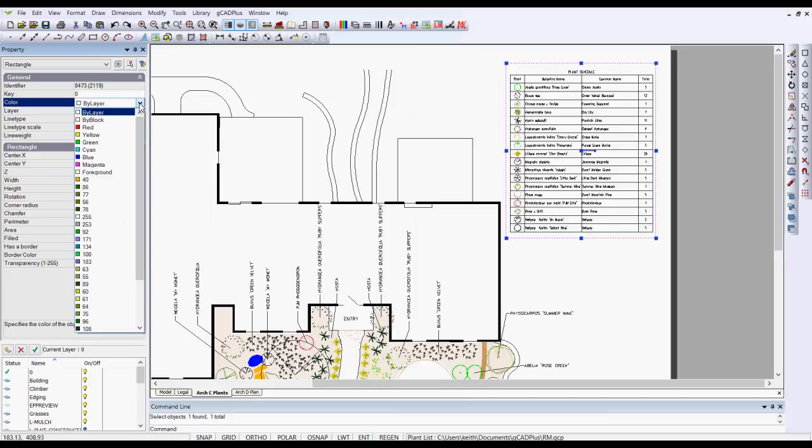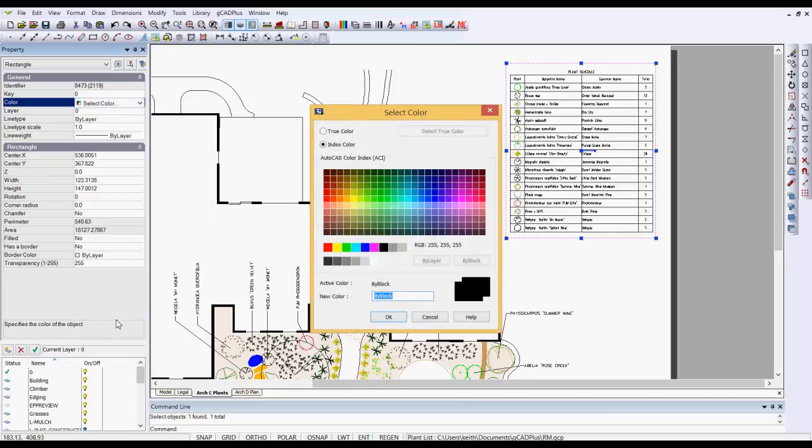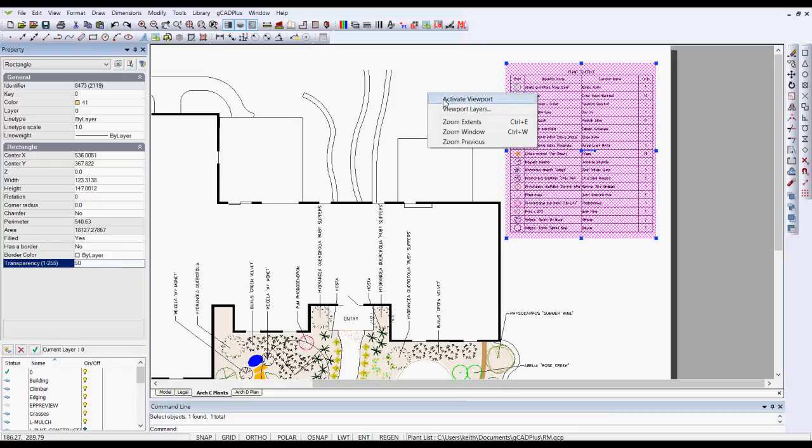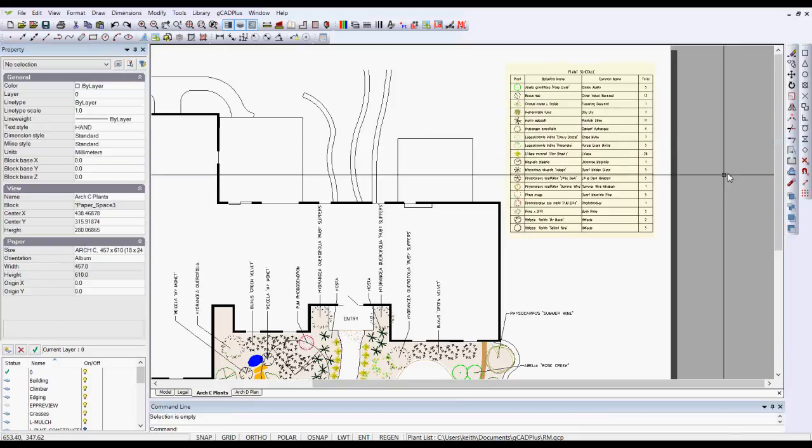We'll make the color of the rectangle some sort of buff color. I'll select a color, take something like this one here, and I'll turn fill on, but I'll give the transparency maybe only 50, might even have to go less, and we'll click out here and unselect all.